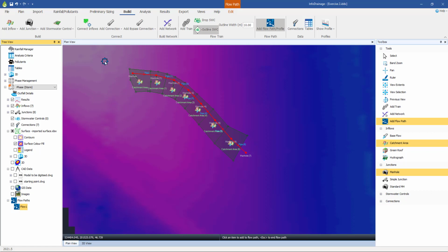So essentially the process is run the no surcharge test and we size and gradient the pipes based on that, and then in the second stage we check them to ensure that during these larger storms there is no flooding. And as I said, that requires a different type of analysis. It's a dynamic volumetric analysis as opposed to the no surcharge case, the first case, which is a steady state analysis.